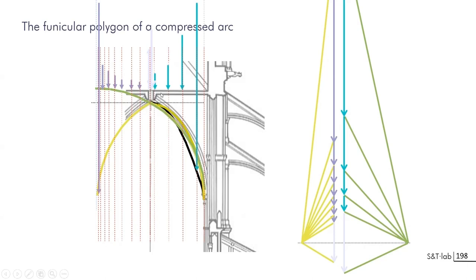You can see if you divide just the applied force at equal distance, we need more and more important forces on both sides on the right. And if this is the load, so this is a case of an arch, for instance, and in the case of vaulting, you will have to distribute forces all along the arch, and you see that these loadings are growing when you are going on the side. And actually, again, you will have the difficulties when your line is getting vertical on both sides, so you have to interrupt it just before, and use, for instance, flying buttresses to create these forces.